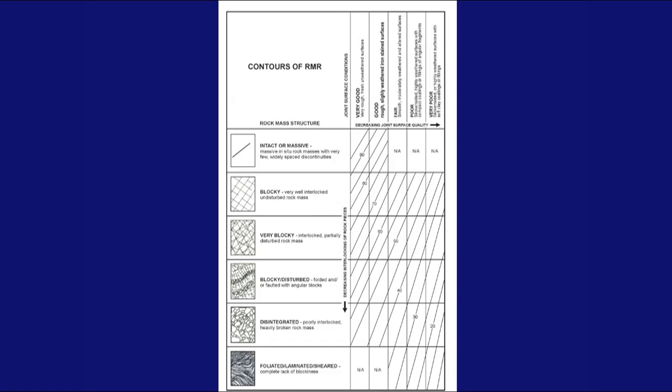Here we have an exposure of rock, and you can see in the lower portion there, you can actually see joints, you can see the rock surfaces exposed and so on. Just have a good look at that and have a good picture in your mind as to what that rock mass looks like, and then we will do a GSI classification of that. There's no doubt that that rock mass would be described as very blocky. And there's sharp edges to the blocks, but there's a lot of discoloration as well. So the value for that would probably be in the range of 50 to 60 for the RMR.